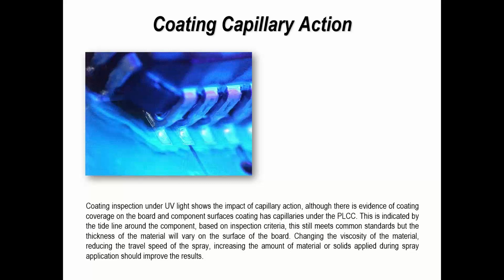So it's only a thin coating underneath the package, so it's not contacting the top of the body or anything, and it's gone all the way around the leads, but you get this weird drying mark, if you like, around it. And you see it on QFPs. You certainly can see it sometimes on LGA packages, LGA QFN packages, but I tend to see it more on QFPs because you've got a large surface area and the material is just literally sucked in underneath the package, just like two bits of glass. If you put a droplet of water, it capillaries between the two.